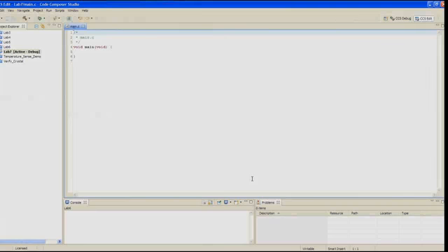The UART code utilizes timer A2, so we'll need to remove the dependence on that resource from our starting code. Then we'll add some trip point code that will light the red or green LED, indicating whether the temperature is above or below or inside some set temperature. Then we'll add the UART code and send messages to the PC.